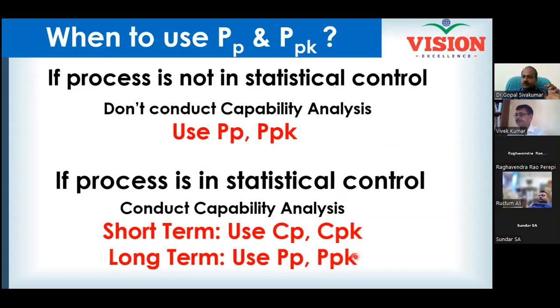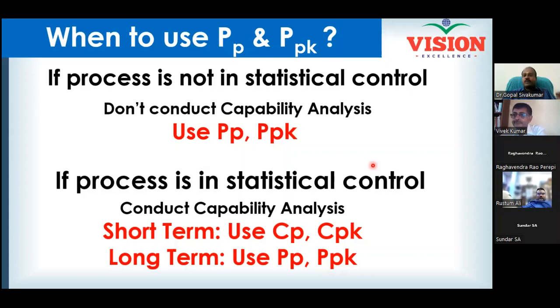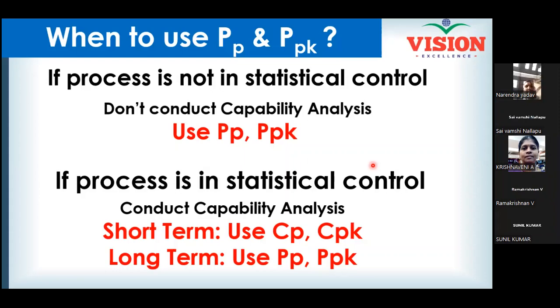All of you understand when you should conduct the capability study? Yes or no? Do you understand, all of you? Yes, sir. So the point is, you can conduct the capability study if the process is under statistical control. How do you know whether the process is under statistical control or not? Plot a control chart. If you get all the points inside the control limits, the process is under control.